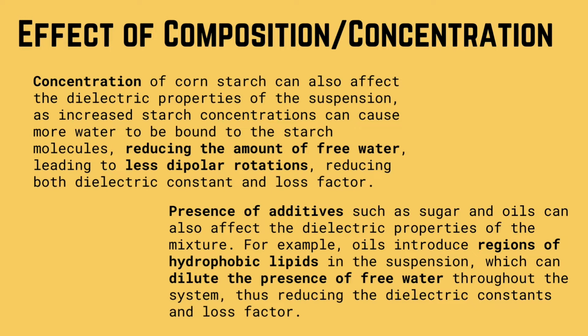And then next up is the presence of additives such as sugars and oils. For example, oils are known to introduce regions of hydrophobic lipids in the suspension, and this will dilute the presence of free water throughout the system, and it will also reduce the dielectric properties and reduce the microwave effect on the system.